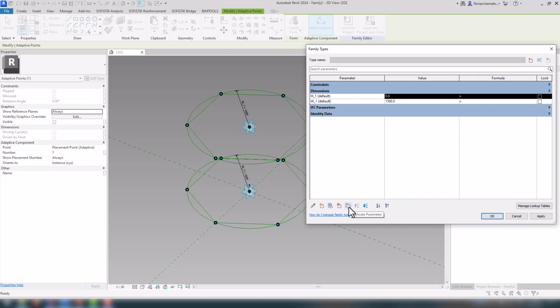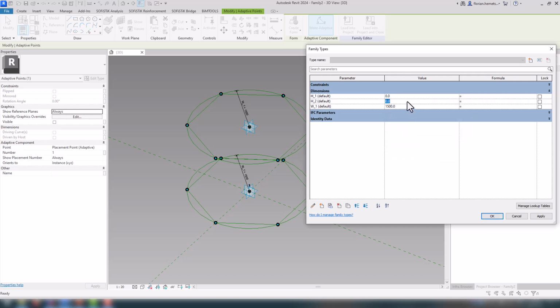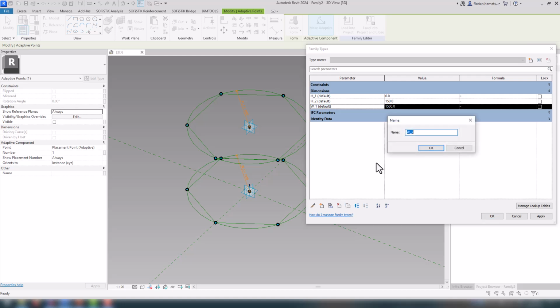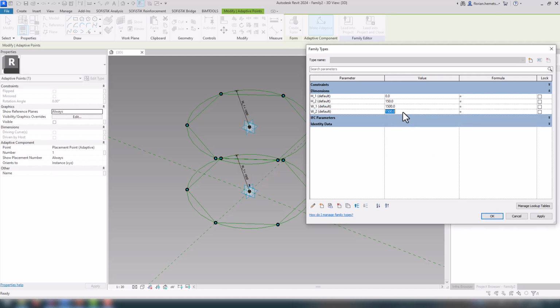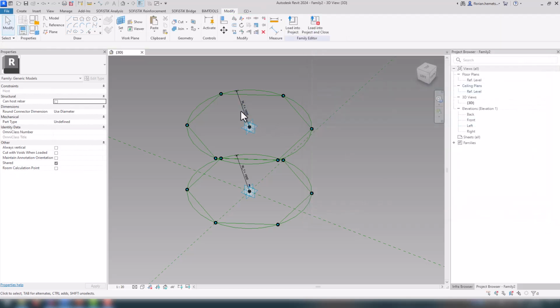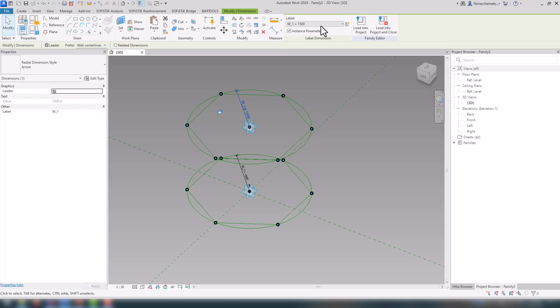All right, so next up is the height number 2 for our parameters over here, and I will just very quickly use the duplicate tab, and it recommends already height 2, which is set to 150. I want to do the same for my width number 2, which is also already recommended width 2. And this one we want to set to 1400. Click on OK, these parameters are now available.